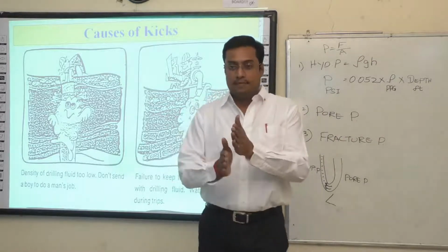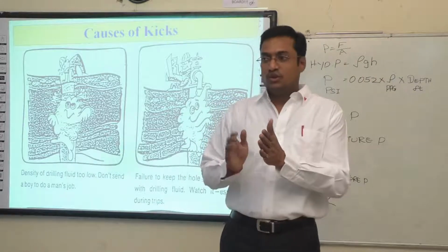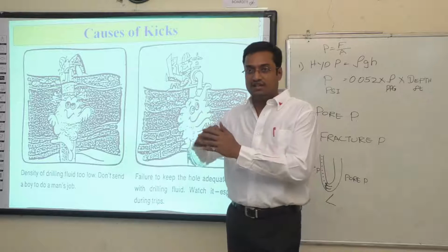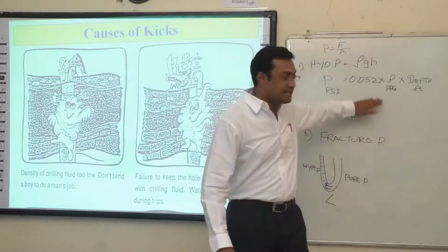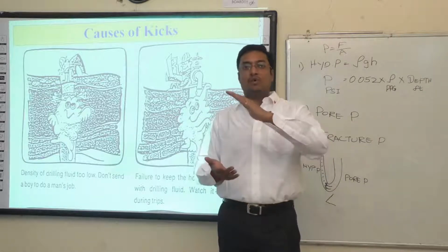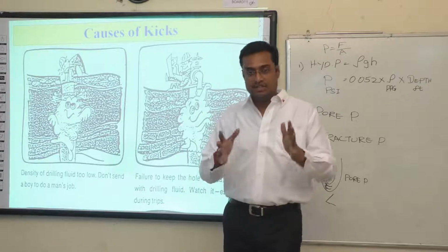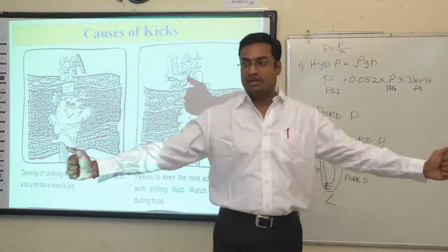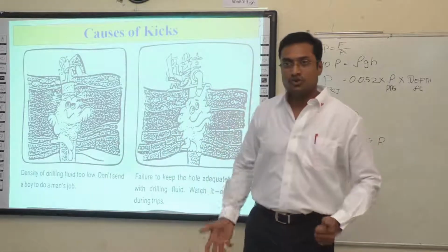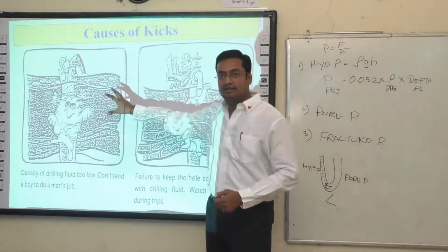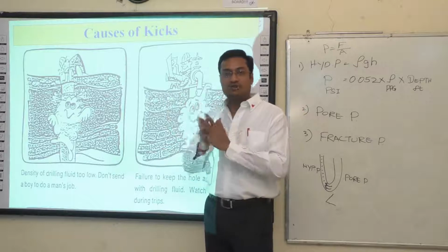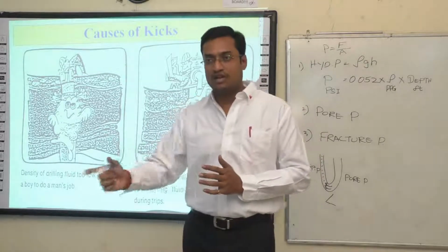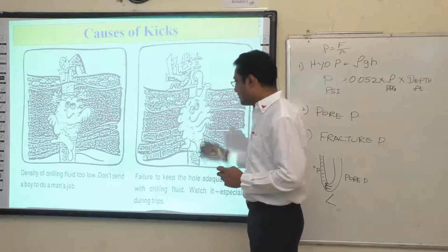So as you go deeper and deeper, you have to keep increasing your drilling fluid density so that the hydrostatic pressure is always more than the pore pressure. That means, in other words, you are giving a small boy a very big job, which he cannot do. So you have to send the correct man, or you have to use the correct mud weight, mud density to control the pore pressures. Next.